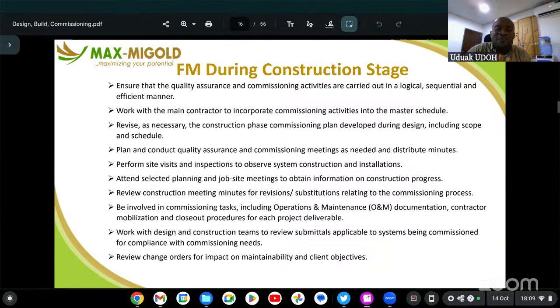So before the commissioning needs, part of it is the compliance, for instance, the warranty, and whether it really meets commissioning needs, if it has been fully installed, if the design is fine, if there are no issues with the system, if there are no dents, for instance on the fins of the outdoor evaporator, or a bit of dents that could cause leakage, with the outlet pipes, the refrigerant pipes. All these are things we need to check during the construction stage to make sure there are no issues with the system.